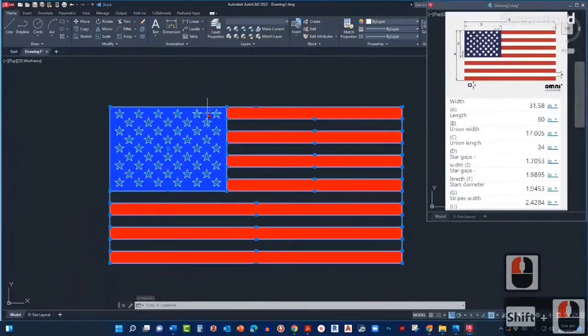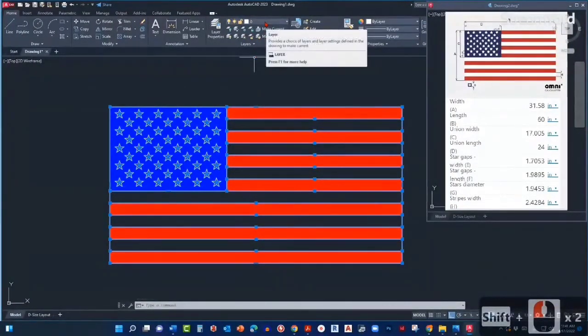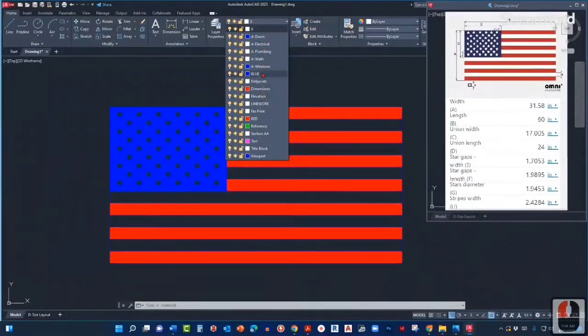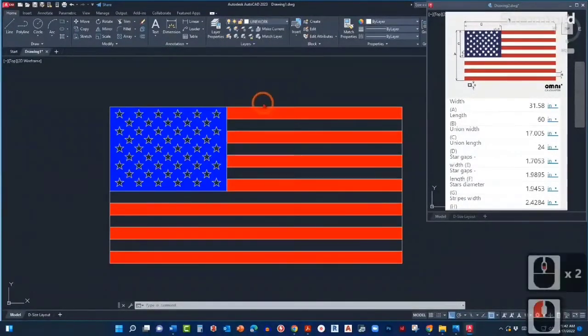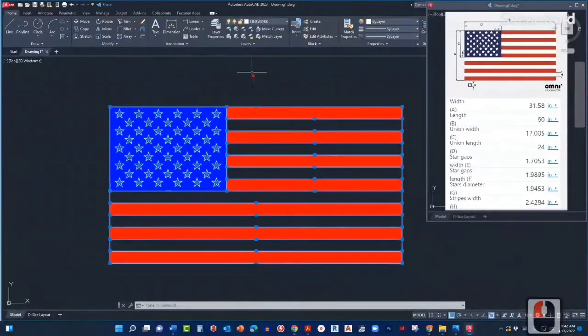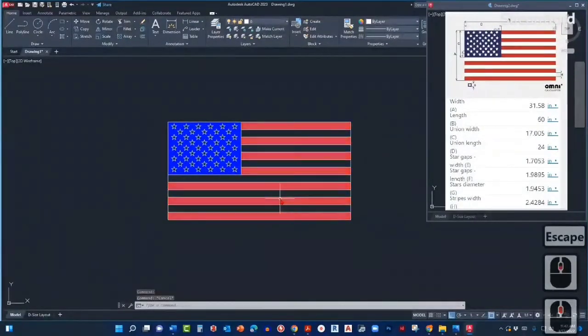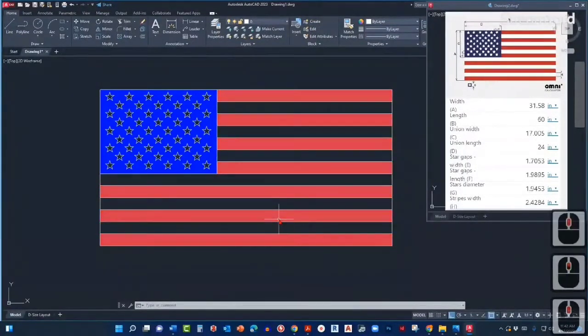Let's select this other blue hatch, and let's deselect it. So again, we are ready to place them on the correct layer, in this case line work. Where is line work? It's right here. All right, so everything is ready now to show you how to export your drawing as a PDF.